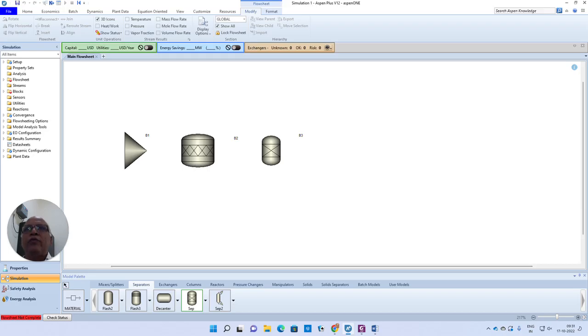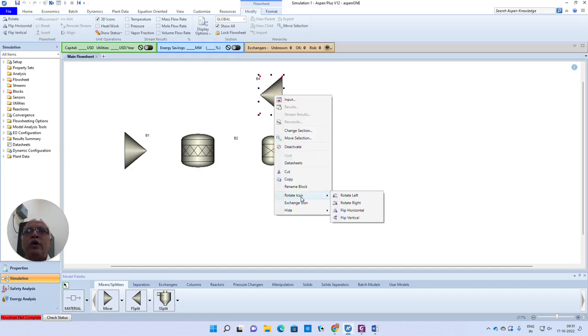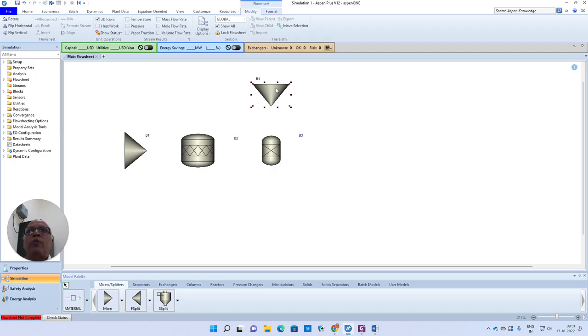Then the bottom can probably be complete ammonia, and the exit is going to contain unreacted nitrogen, hydrogen and also argon. So to avoid the buildup of these inerts, we are going to use a splitter, which is going to take some amount of purge. So 5% is taken as purge and the remaining 95% is recycled back.